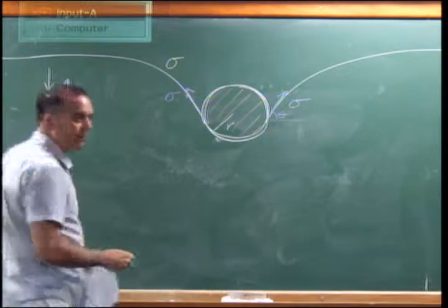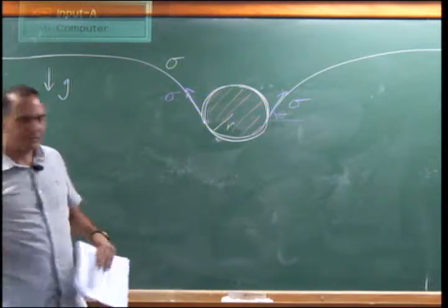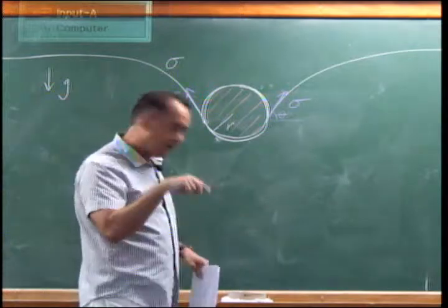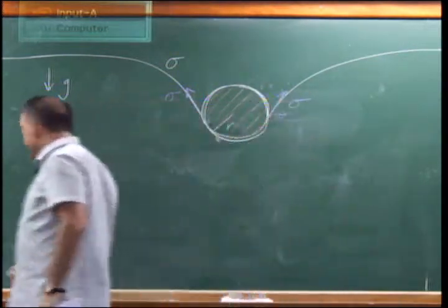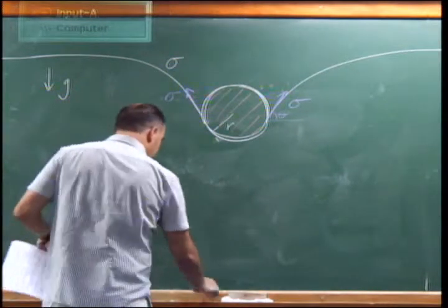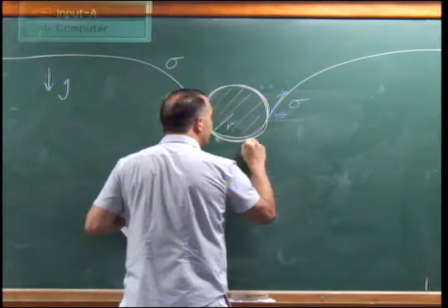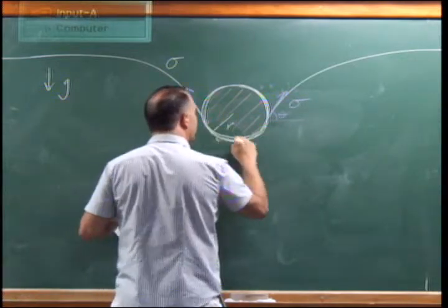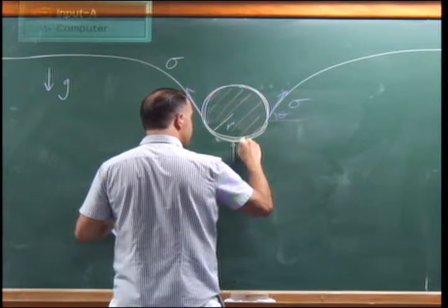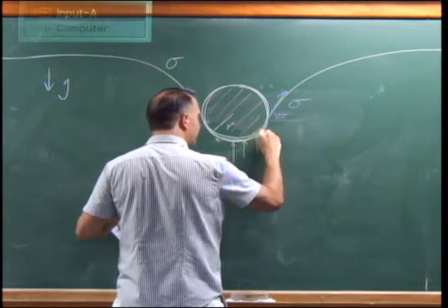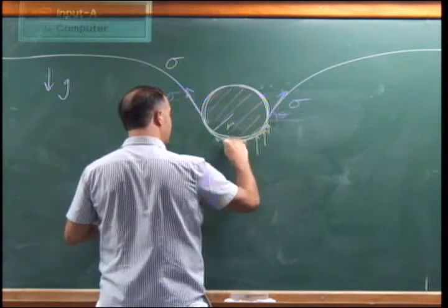And then there's going to be the hydrostatic pressure, right? And hydrostatic pressure we compute just as we did previously by integrating. We calculate the hydrostatic force by integrating the hydrostatic pressure over the surface in contact with the fluid, which is this surface, right? So we know along this surface there's hydrostatic pressure everywhere, which is decreasing as you get closer to the surface.